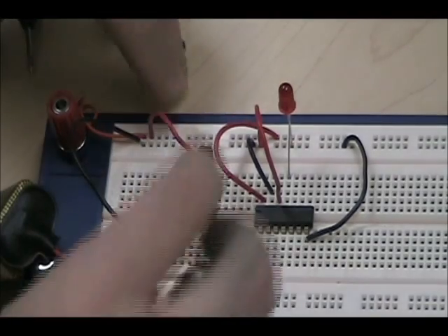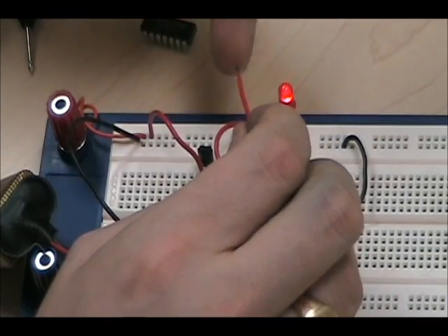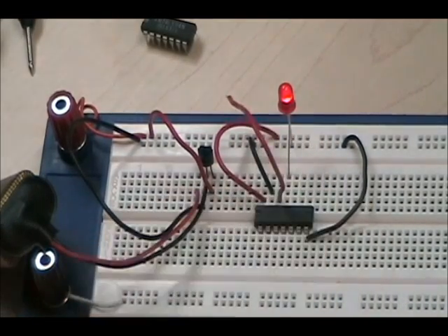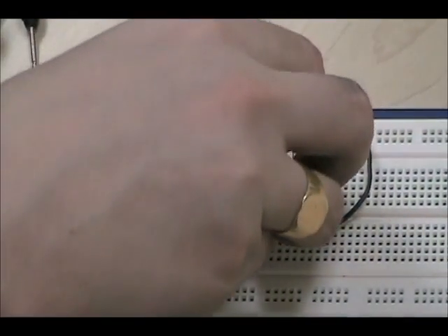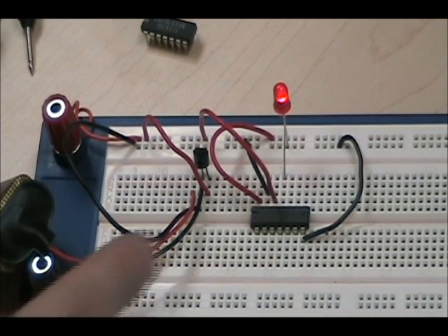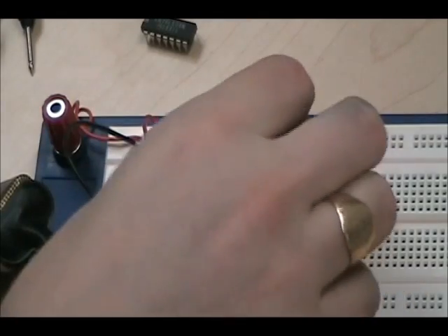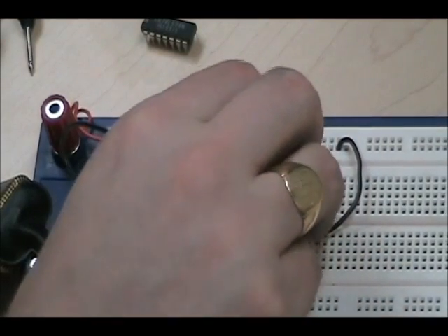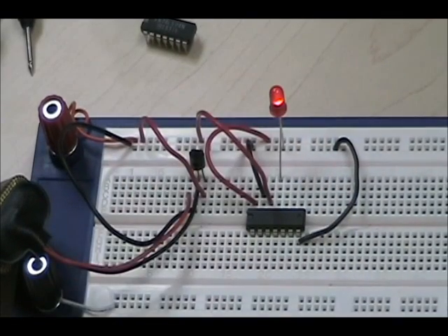As soon as I take any of those off the ground line and leave it floating, it's automatically assuming a logic level of 1. High or low logic. 5 volts, high logic. 0 volts, 0 logic. So now one input is grounded, one input is not grounded, one input is held at high. So I can do whatever I want with that second one. I can ground it, I can put it at 5 volts, it doesn't matter, because one of the inputs is already at high logic. So it doesn't matter what I do with the second one.